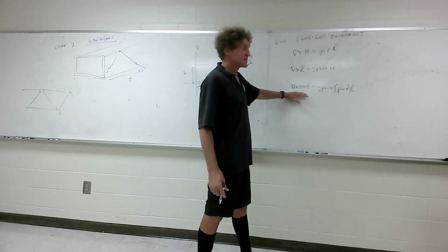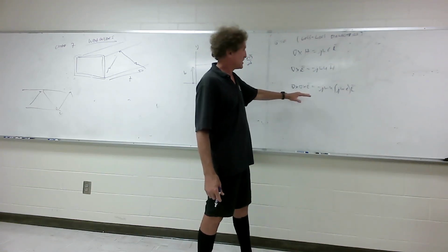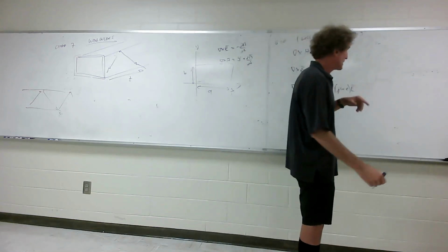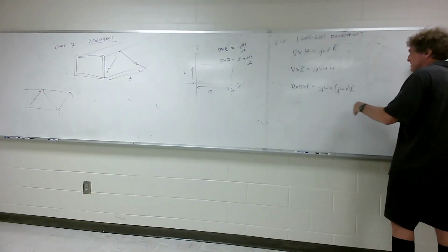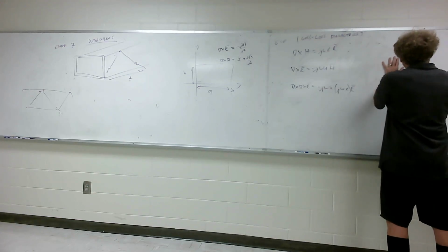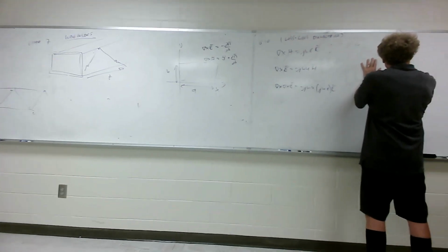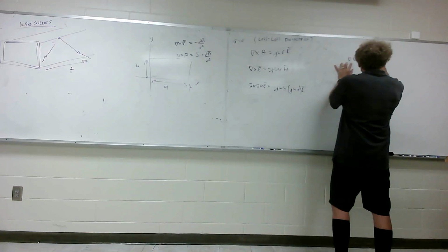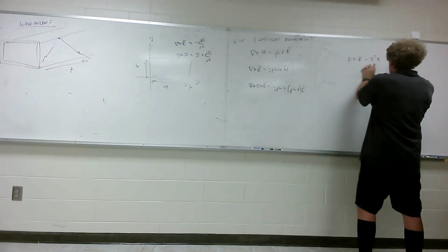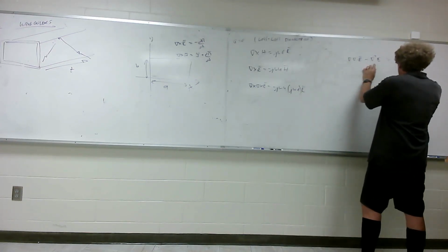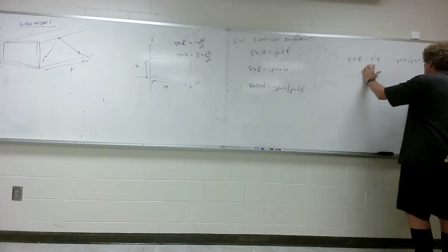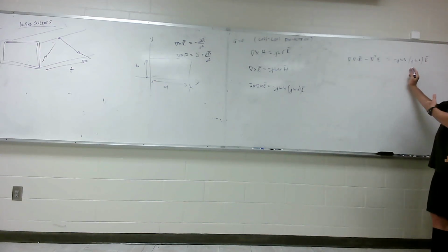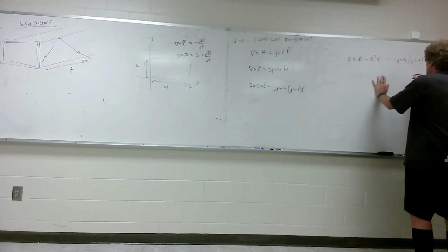All right, back to this thing. Do y'all agree with that? Now I'm going to use the actual equation; they'll never ask you to solve the whole thing, I don't think, unless you're applying for graduate school. For this one, it becomes gradient of divergence of E, just as before, and it's minus del squared of E, and that's equal to minus j omega mu times j omega epsilon E. And here we see j times j is equal to minus 1, where the minus becomes plus.